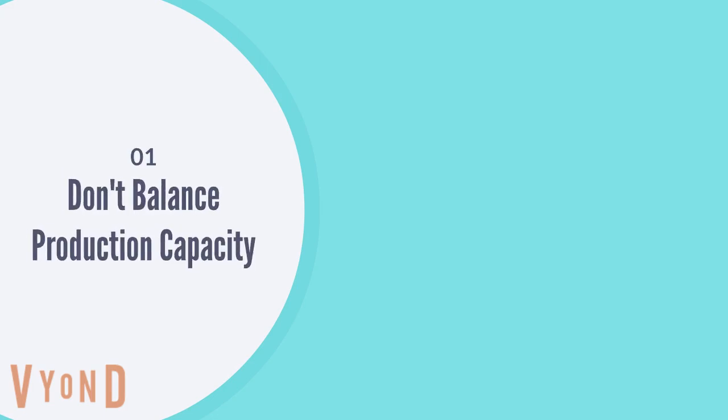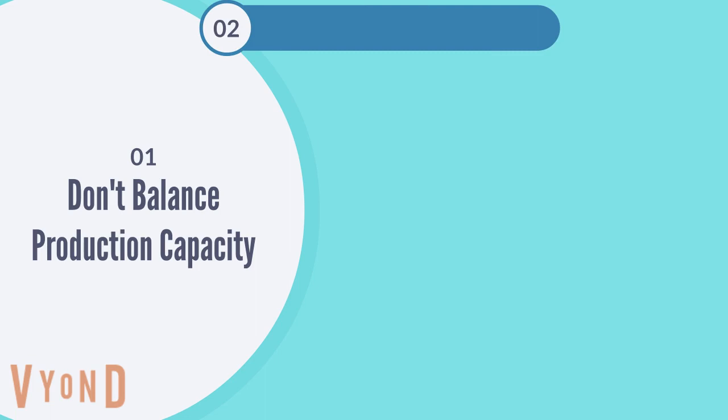Last, I would like to wrap up today's session with the 9 TOC principles for production scheduling. The first one: don't balance production capacity. Balance material flow instead. It is impossible to balance the production capacity. We have to adapt to the changing demand by synchronizing other processes with the bottleneck. The second one: the utilization rate of a non-bottleneck resource is not determined solely by its capacity but rather by the system's constraints. This means that non-bottlenecks won't achieve a 100% utilization rate.